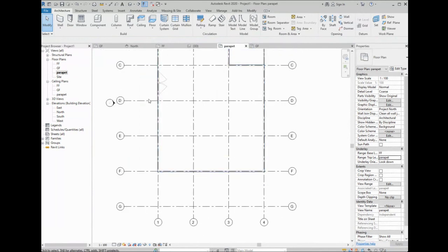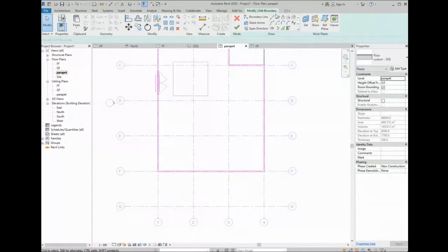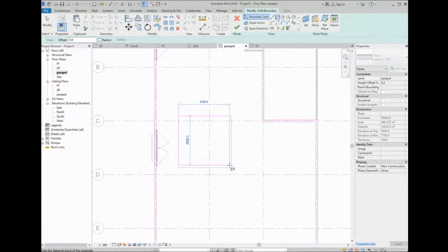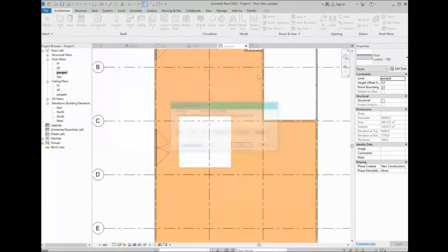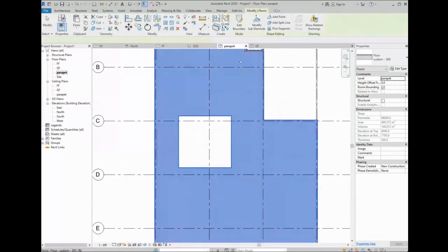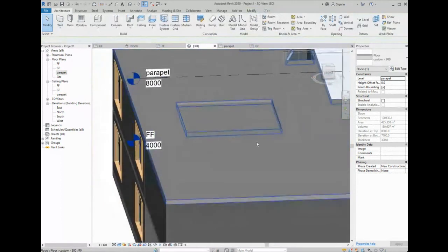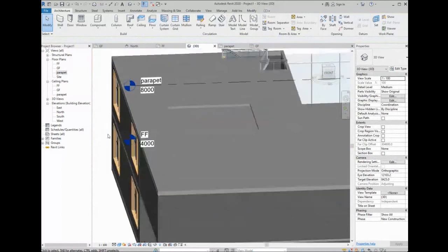It's supposed to show. So basically what you need to do is you can create an opening here, and this is, okay, it's here. So you'll create this one from here to here. So it will be an opening. Click on OK. Yes. Okay. Let's go to 3D. So now it is opened, and then you have this one in the lower level.